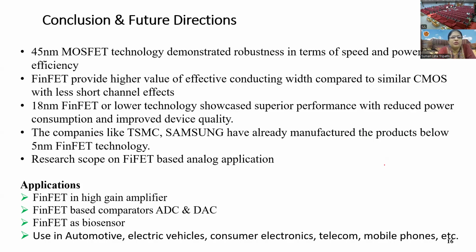So the advantage, if we compare it with the MOSFET: if we talk about 45 nm, because the size is bigger, obviously it will demonstrate better speed and power efficiency. But if we go below 45 nm, then FinFET will be effective because of less short channel effect.